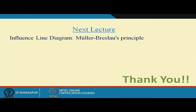Now, we stop here. In the next class, whatever discussion we have had so far is that, in order to draw the influence line diagram, we actually need to solve the problem. We need to find the support reactions, get the expression for moment and shear, and draw the diagram, and essentially influence line diagrams are the graphical representation of those expressions.